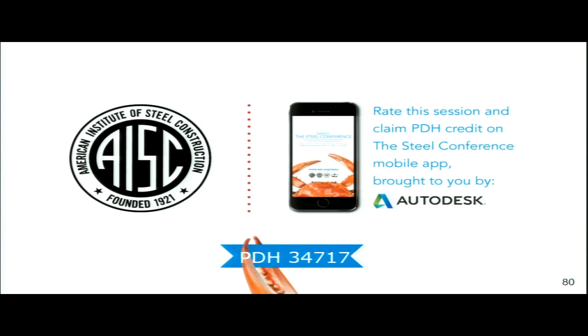To go up a little bit is no problem, because the MEP engineers are the ones making this stuff, and what do they care about? They care about higher frequencies, right? So that's not a problem. The time we really find ourselves working on this is when you have an MRI going in, and they want to make sure that the average spectrum is below some value from 1 hertz all the way to 80 hertz or 50 hertz or some number like that. Then we have to measure all those higher frequencies, and if one of them is popping up above the limit, you have to figure out which equipment is causing that and go isolate it. That's when we are usually dealing with equipment-induced vibration.